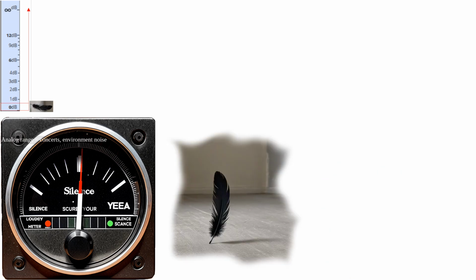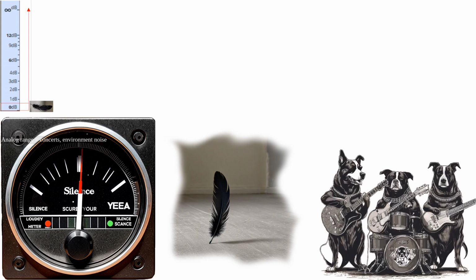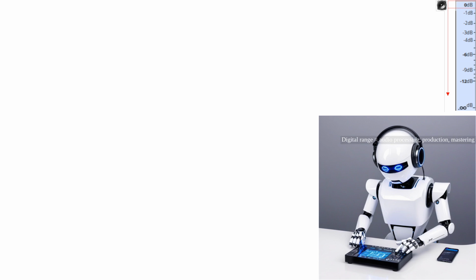In the analog world, decibel are compared to the most quiet sound measured, which is referred to as silence, but it's not strictly silence. This point is labeled as 0. So a music concert being 90 decibel loud is 90 decibel louder than silence. Meanwhile, in digital audio processing, the point of reference for loudness is set to the maximum level a system can safely output, which is labeled as 0. So all audio loudness values are usually negative because we talk in reference to the maximum of 0. I know this concept of reference points is confusing at first, but it will become clear in a moment.